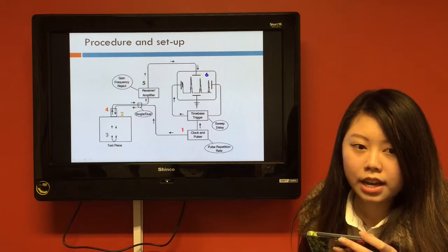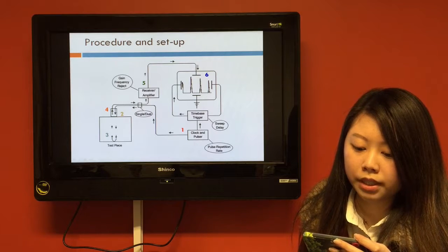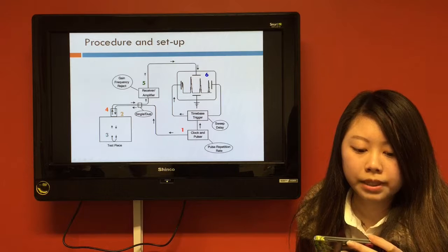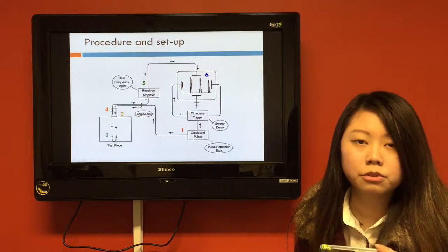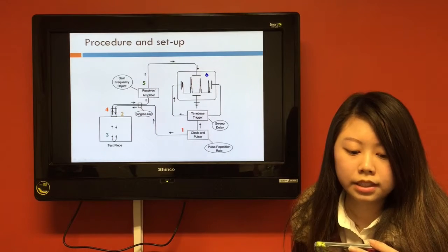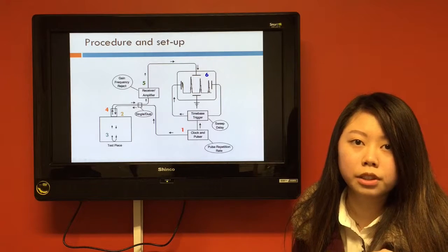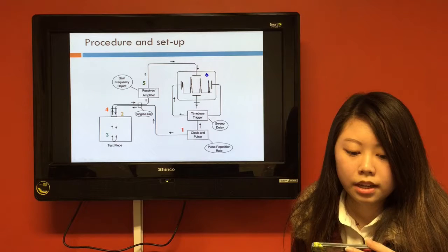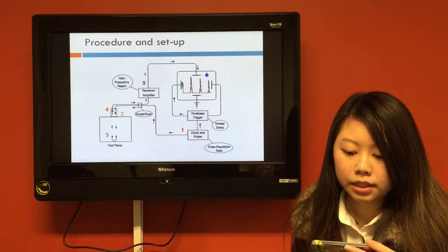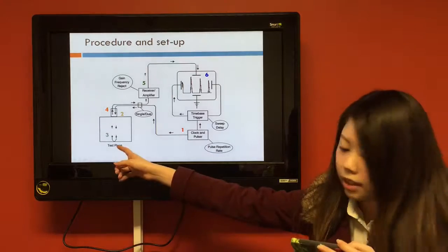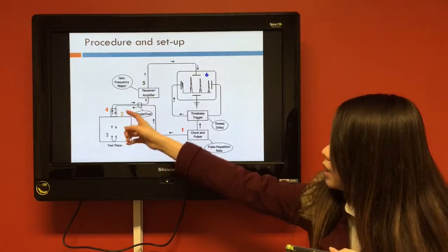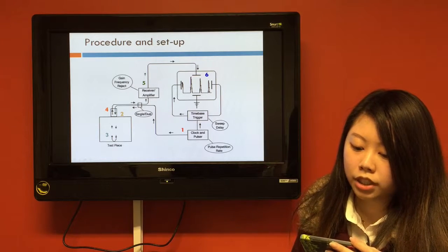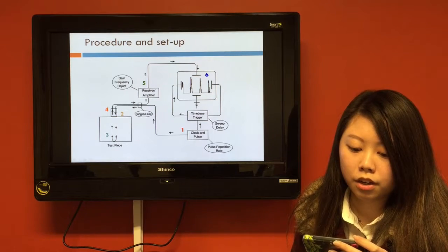to the transducer and is converted to mechanical vibration. Then it enters the steel piece. The vibration will travel along the sound path in the steel piece. The spot is moving horizontally across the CRT in this process. The energy in the steel piece reflects from the back interface to the transducer, and then the transducer will convert the energy back to voltage,